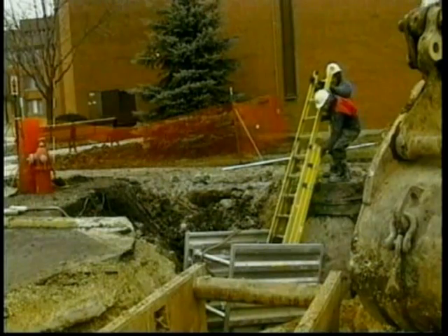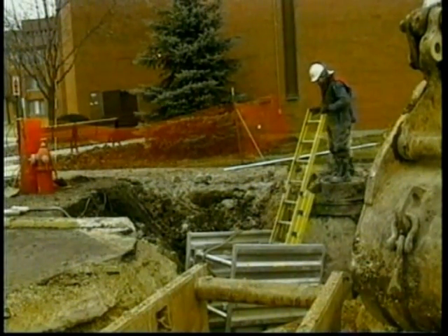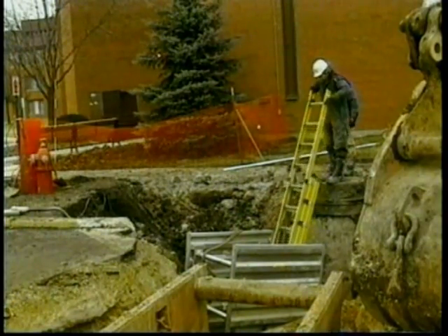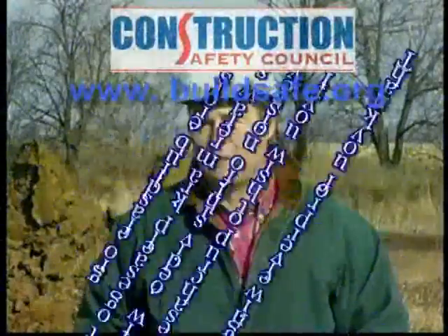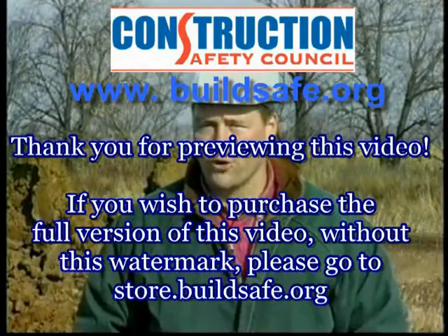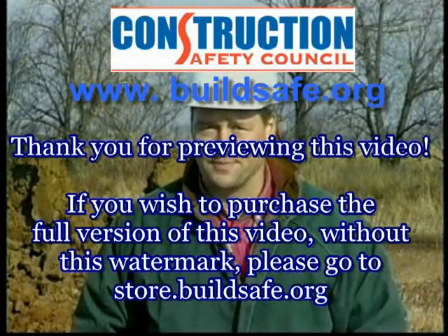First, a safe way into and out of the excavation must be provided for employee use. A stairway, ladder, ramp, or other safe means of access and egress must be included in any excavation or trench 4 feet or more in depth. Any means in and out must be located so that an employee doesn't have to travel more than 25 feet to reach it. One further step must be taken before anyone can work in the excavation.